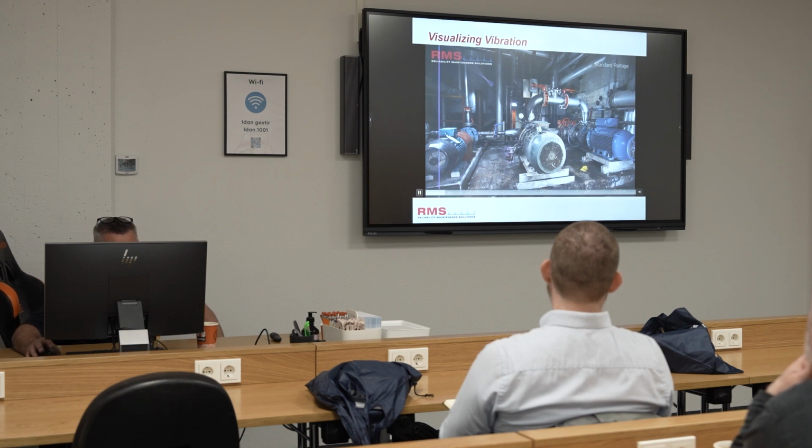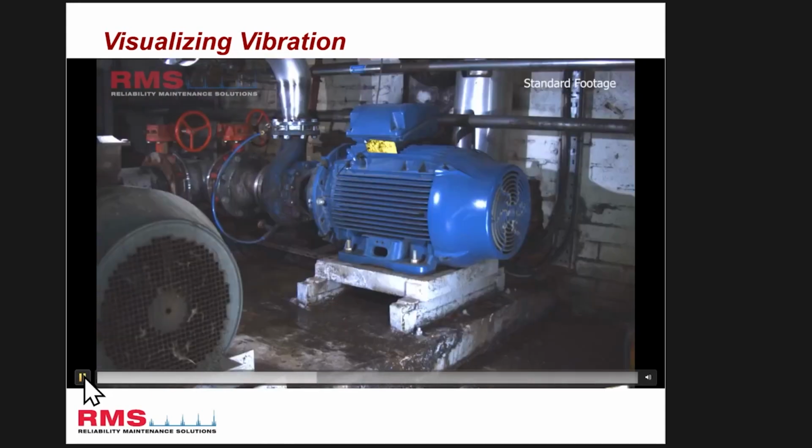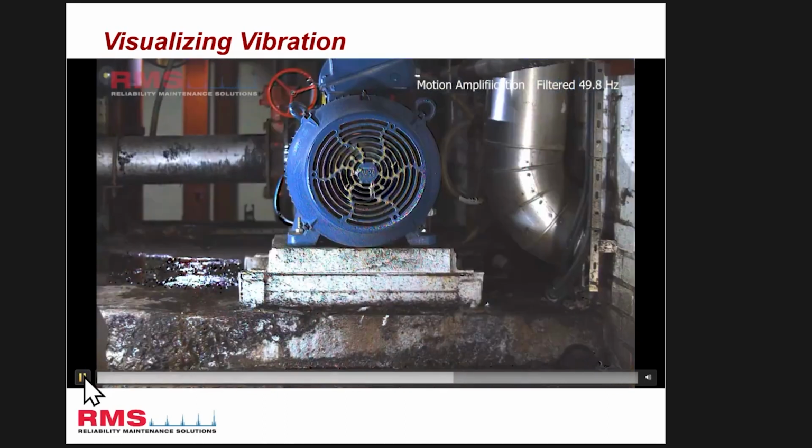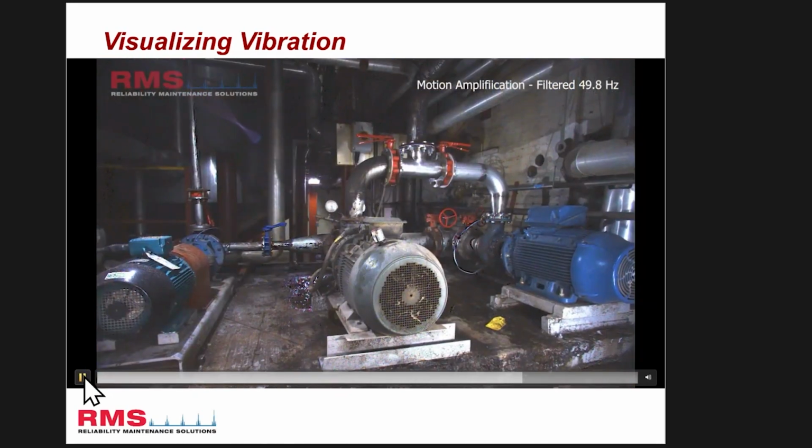Okay, this is what's happening with that pump running. This is using a colour, and this allows us to zoom in into any little component, and you can see what's happening on each situation. Remembering, this isn't very good. You can't see this with the naked eye. This is how motion amplification works with vibration.